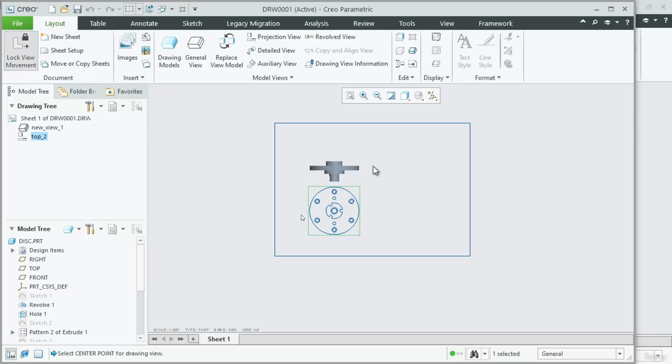So this is the way you should approach. This is a professional way. First you should make your perfect drawing according to the customizations that you give. After that, save the customizations as a standard DTL file, and that file you can reuse again and again in any model, in any drawing you like. Most of the companies that you work for will have this standard DTL file according to their standards, so you can use those DTL files directly. In the next lecture, we will know how to add new drawing sheets into our drawing file.